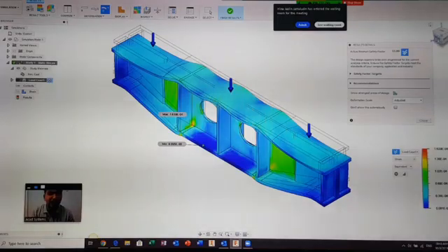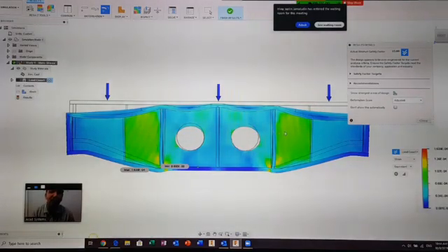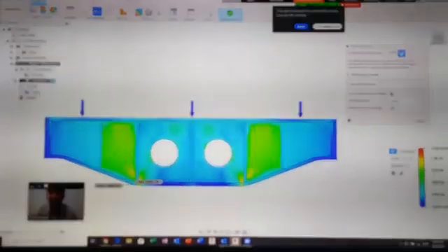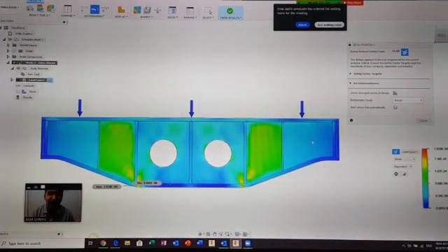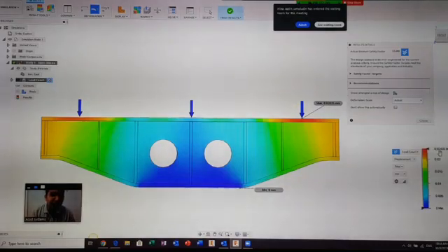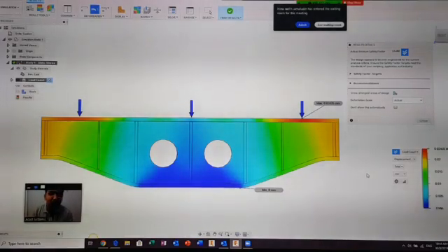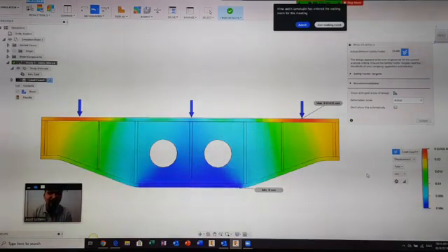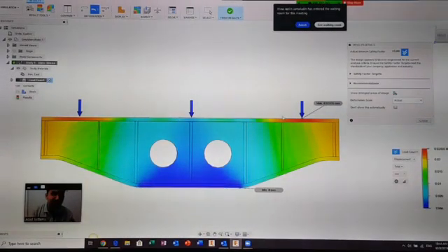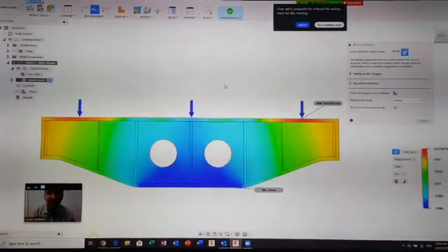So actually for this load, it's been scaled or adjusted to show us the deformation. If you select the actual one, you can see what really happened. The actual shape means, let's check the displacement. Here it is 0.02 mm. That means this displacement is only a little bit from your original location. So it means this part can handle the load itself.